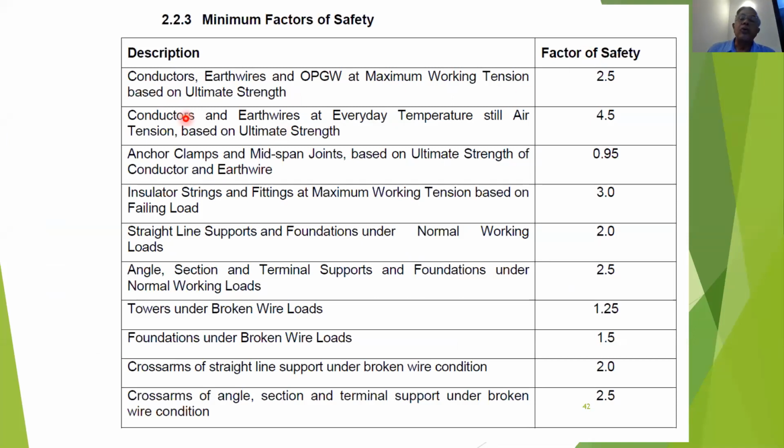Now, sorry, this is the maximum. So maximum in the sense, okay, when does the maximum conductor stress occur? That is at the lowest temperature and maximum wind.